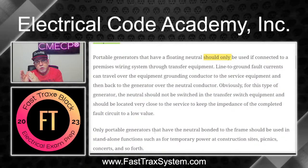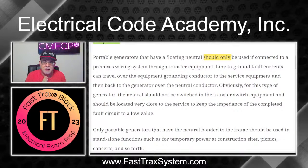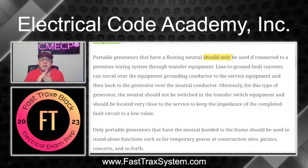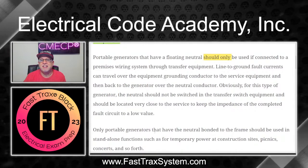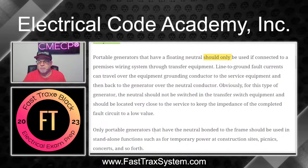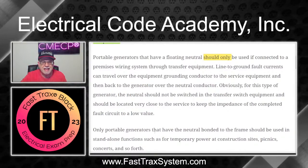And so when you have that connection and you get, let's say, a transfer switch and you don't pay attention and you get one that doesn't switch the neutral, then you're going to get parallel paths of neutral current traveling, and that is an unsafe condition, okay? Because basically you have to understand that what you're dealing with is parallel paths of neutral current. So it can be really unsafe. But we'll look at all that in an example and kind of show you what can happen. But don't worry, we'll dig into that in a minute.